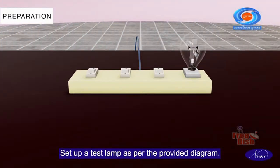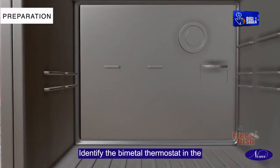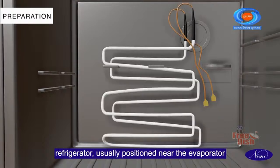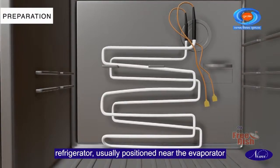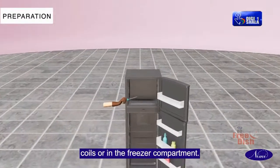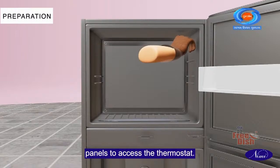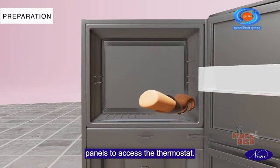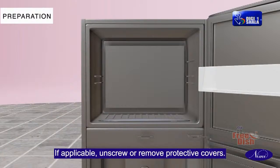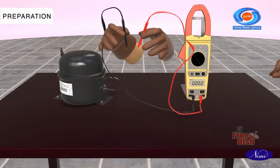Set up a test lamp as per the provided diagram. Identify the bimetal thermostat in the refrigerator, usually positioned near the evaporator coils or in the freezer compartment. Remove any necessary covers or panels to access the thermostat. If applicable, unscrew or remove protective covers.